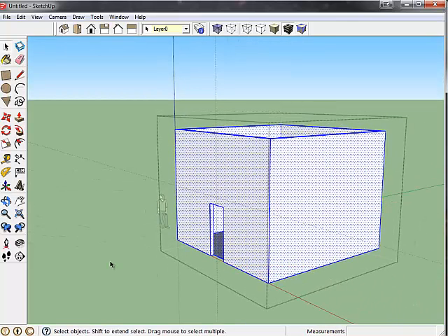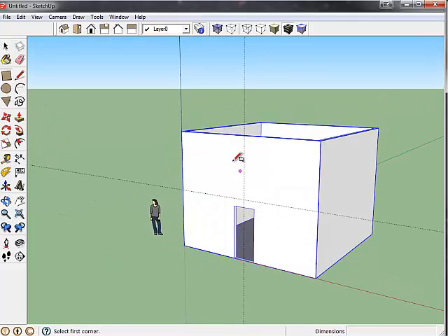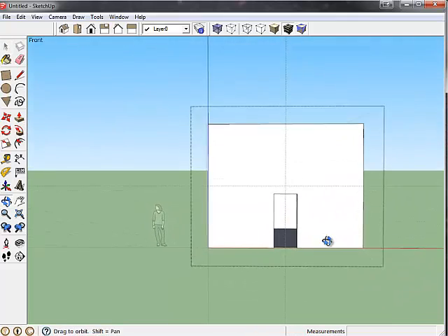to start drawing. This is one of the more difficult things that people constantly forget. So if you're at a case where you are drawing on top and you cannot push pull in, it's because you are on top of the group and you did not draw what you wanted to inside. Let's double click inside of the group.